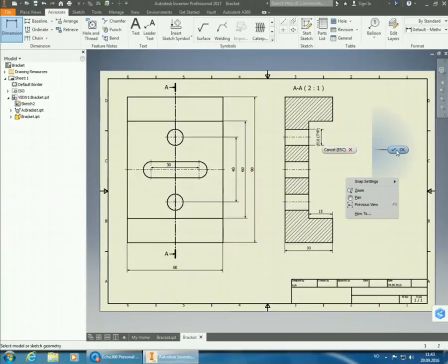So we exit the dimension function. If I don't exit the dimension function, I'm just going to open up the window where I entered tip earlier. So I exit the dimension function, because then I can drag and drop this dimension. So I mark it with my mouse pointer like this, just move it over it, and then I click and I drag. So then I get the dimension on the outside instead. So it becomes a bit more readable by doing it this way.